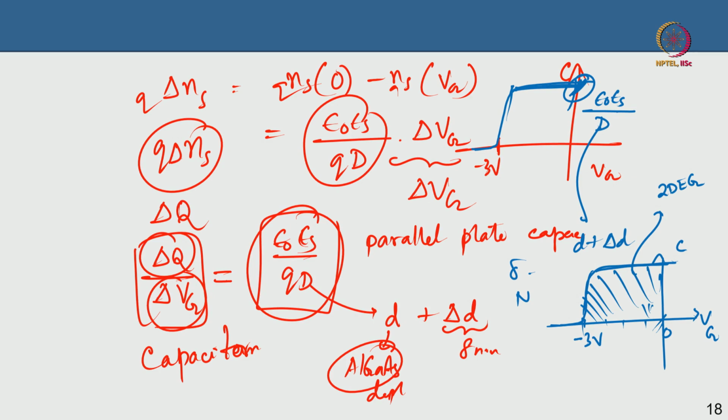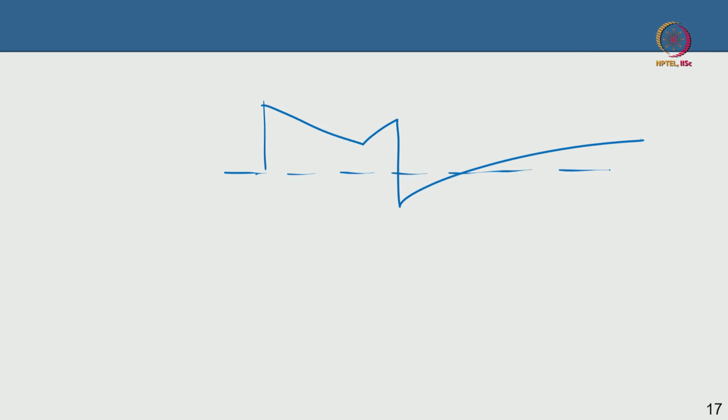Okay. So that is what we discussed, but this does not matter whether it is a delta doped layer or a uniformly doped AlGaAs layer. What I mean is that till now we were talking about a delta doped layer where there is a delta doping and there is a 2D electron gas like that. Okay. So this entire layer is AlGaAs, but there is a sheet of high doping here and you can bring it as close to the 2DEG interface as possible to get a very high density of electrons here.